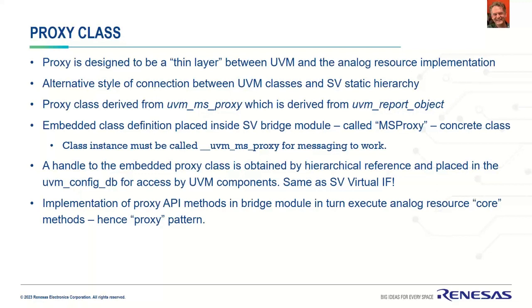Then if you have this system set up, you can pass a handle to the proxy class by hierarchical reference in the test bench, and put that into the UVM config DB, exactly the same way you do it for a virtual interface.